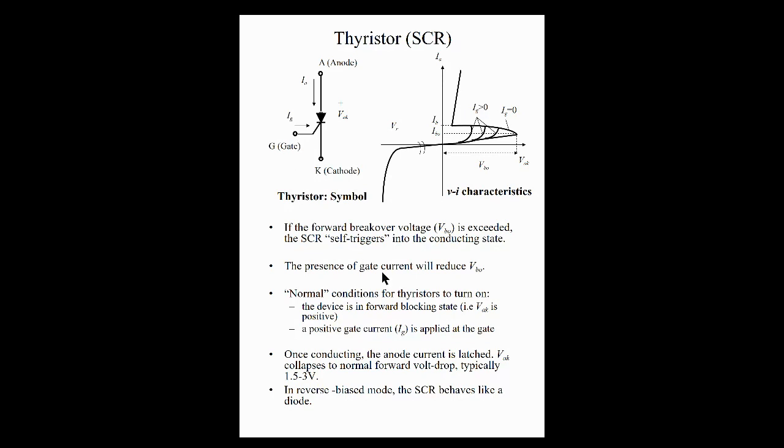Very important. How can we turn this device off? There are techniques we refer to as commutation techniques that we can use to bring this device to the off state. There are two methods, either forced commutation or natural commutation. Right, so with the forced commutation, as long as we are able to introduce some kind of circuitry, we reduce the current flow between the anode and the cathode, right? Then we'll be able to turn this device off.